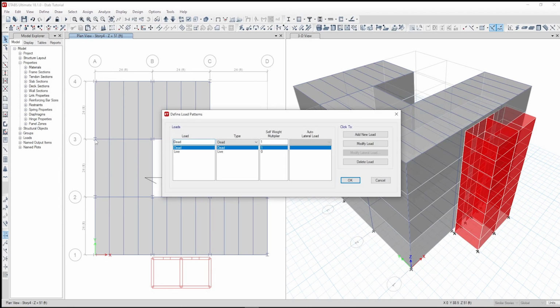The static loads used in this example consist of the dead, live, earthquake and wind loads acting on the building. An unlimited number of load patterns can be defined. This example also applies an ASCE 7-10 static earthquake load and an ASCE 7-10 wind load to the building. The forces that are applied to the building to account for the earthquake and wind load are automatically calculated by the program. Note that there are two default load patterns defined. They are Dead, which is a dead load, and Live, which is a live load.